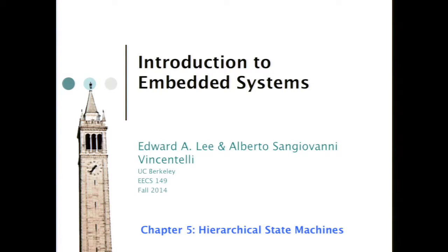We add some notation to the state machines that enables us to handle a little more complexity manually. For example, extended state machines, which give us the ability to manipulate variable values as part of the state machine, and concurrent composition of state machines, where we can take two relatively simple state machines and compose them either synchronously or asynchronously.